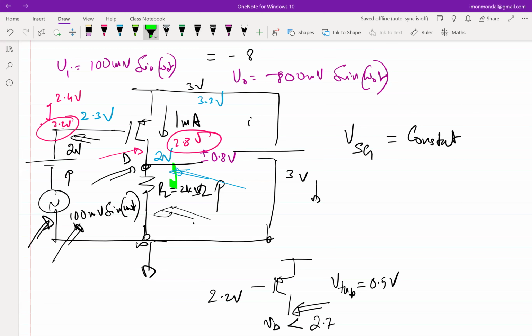Whenever you are taking up an assignment or a project and they say that I want an amplifier of gain of 8, you have to ask a few questions. You cannot simply blindly say that yes, kar denge, right? You have to ask for some other specifications. What is the battery voltage that you are going to give me? What is the load resistance that I am supposed to drive? How much input swing are you expecting, right? So these are three of the important questions that arise out of this discussion.